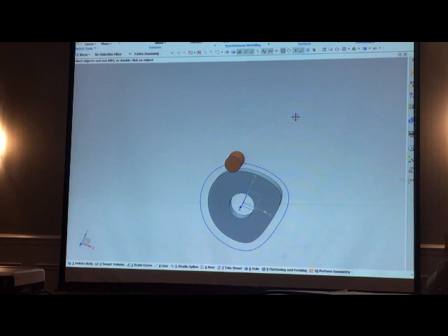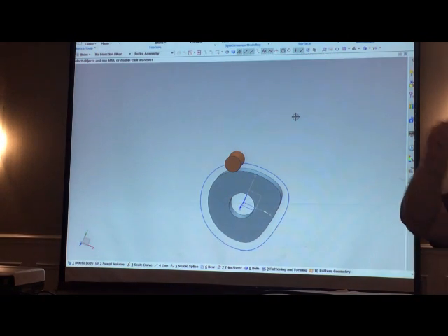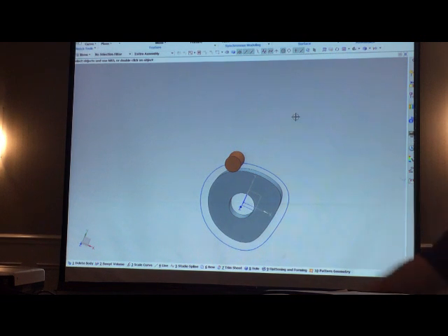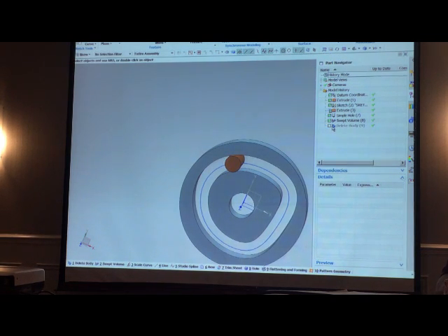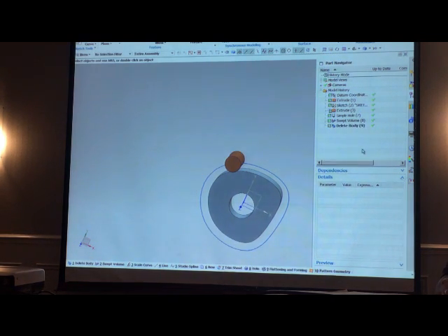If you delete a body in normal NX, you know, just delete something, the feature goes away. In other words, everything would have gone away. So this way, I only deleted the body, and it actually is a feature. See, delete body. If I suppress that feature, it comes back. It's sort of like an anti-feature.